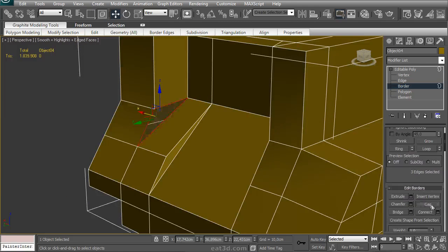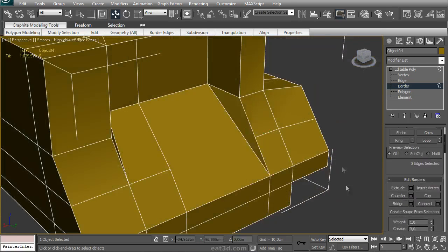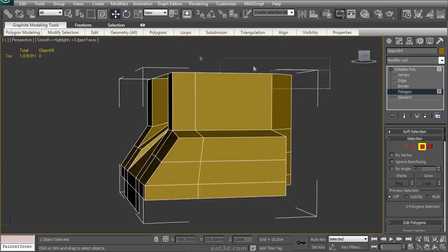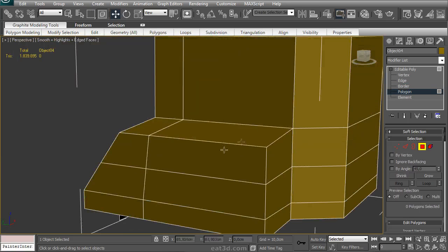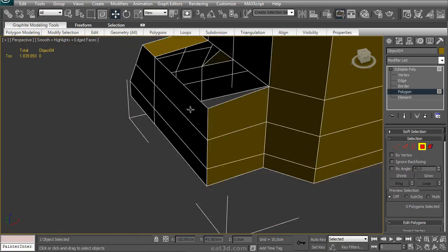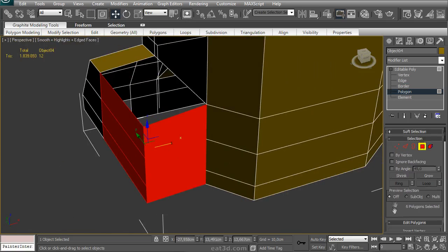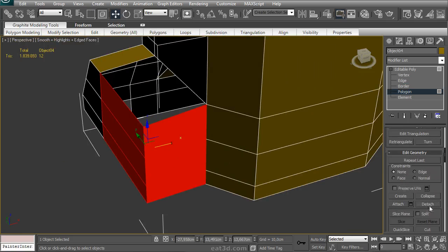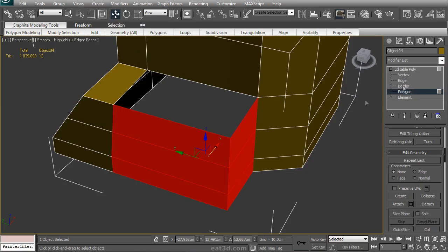Sure, yeah, they're triangles, you want to avoid that for high poly, but for now I'm just going to leave these because I think the basic shape can be done without triangles, so I'll go back to those and fix them later. Deleted the top since I want to do the window, the roof as a separate part anyway. And right now I'm just selecting separate parts and detaching them.